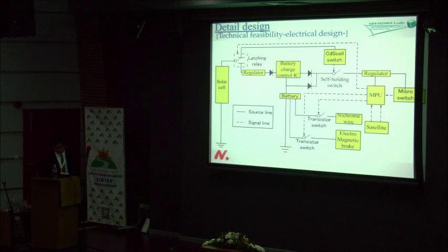If the MPU receives no signal from the satellite for a certain duration, it closes the transistor switch so that the hold release mechanism is activated and the membrane structure deploys. When the MPU receives the signal for the activation from the satellite, it closes the transistor switch so that the hold release mechanism is activated and the membrane structure deploys.